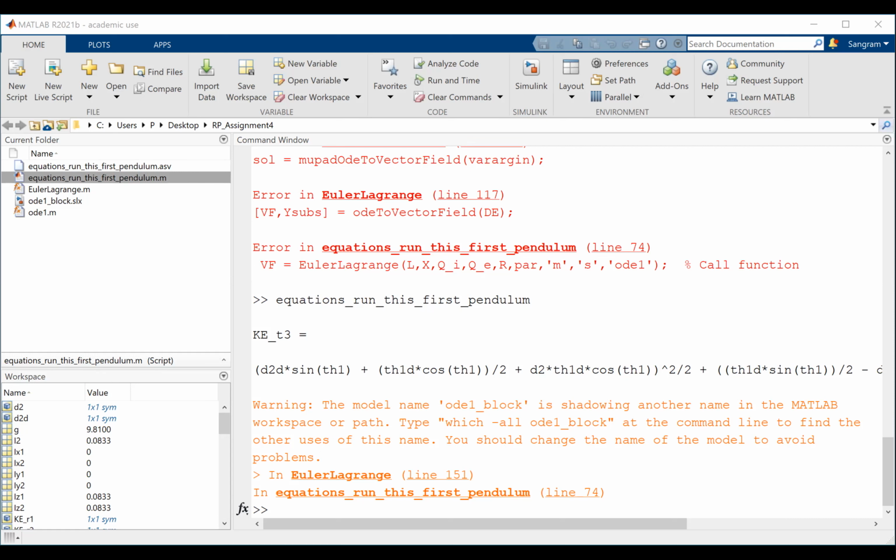So those are generalized internal forces, which means if this robot arm would have had some damping, that damping would enter here. This would be the damping for the revolute joint. Here would be the damping for the prismatic joint. Everyone understood this? In our robot arm, right now, our internal forces are zeros. We assume that robot arm to be ideal robot arm. No friction, no dissipation, nothing. So that's why these are zeros.